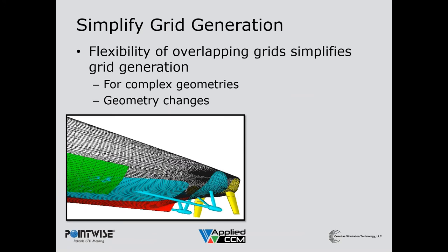One of the first things that overset grids was used for was to simplify grid generation on a complex geometry. We can decompose a complex geometry, such as the ship hull, into different components. We grid the bare hull first, and then incrementally add the more complex geometric components. This has the benefit of not only simplifying the grid generation, but naturally allows you to identify the effect of each component on a performance measure. Find the drag of the bare hull, and then add the skeg or rudders without changing the previous grids. Run the simulation again and be able to predict the change in the performance measure caused by adding the geometry component.